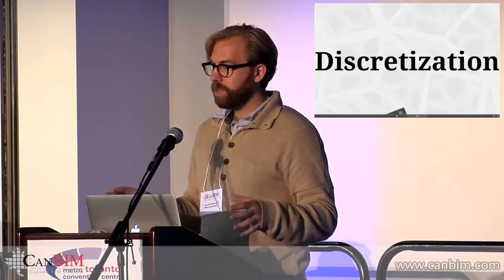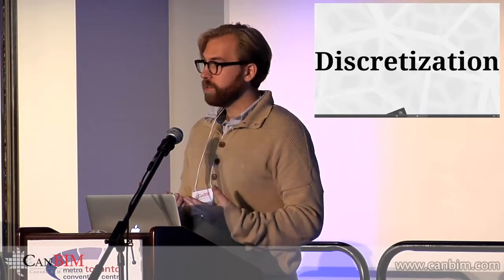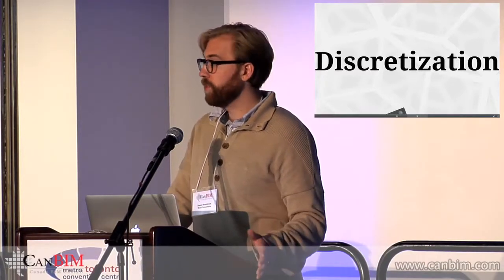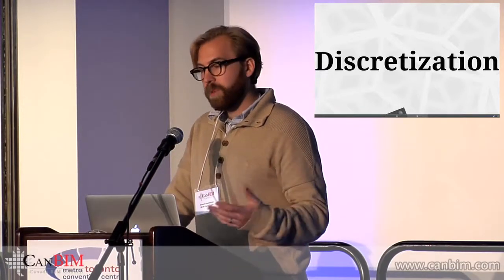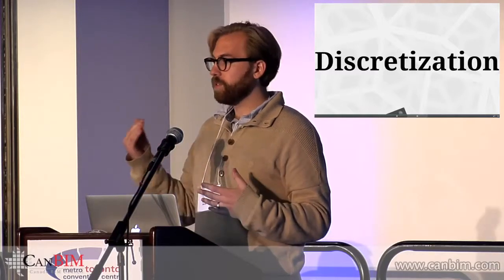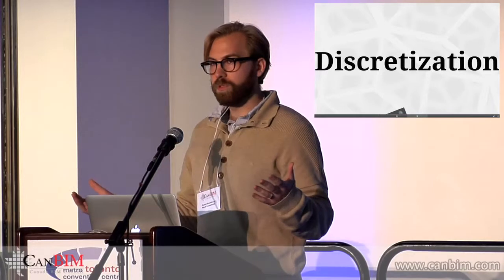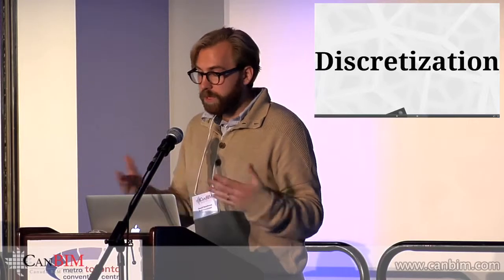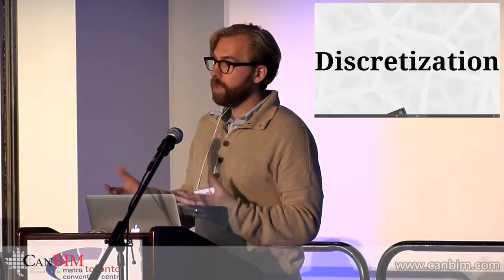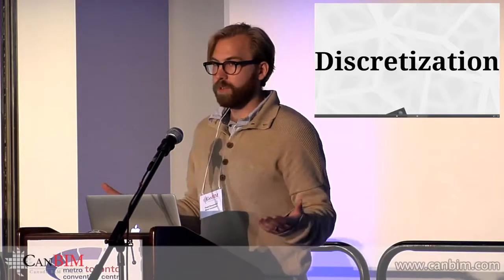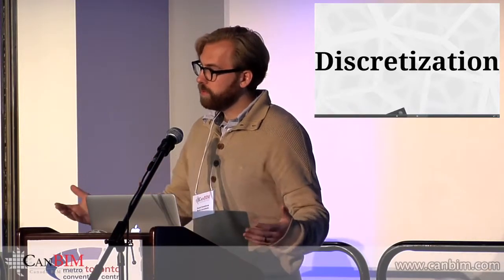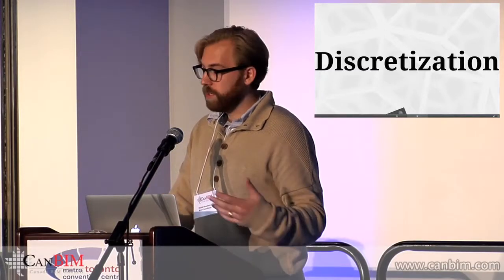So I'm going to get a little bit into the theory of why geometry is so important to this process, and it comes out of this concept called discretization. I'm not sure if some of you might have heard this term before, but what happens in architecture, in the digital model, is it's quite easy to model a really smooth and sexy surface for a roof. But at an architectural scale, it's very rare that anything actually curved gets built. And even if something curved does get built, the scale of the individual components is nowhere near the size of the overall construction. So a process called discretization has to take place, whereby you chop up the original surface or volume into its constituent parts.